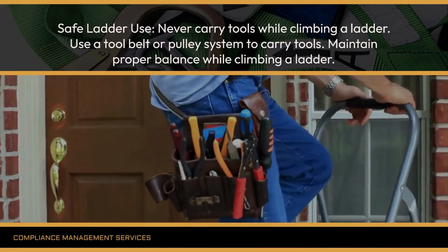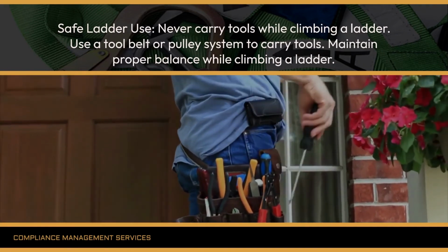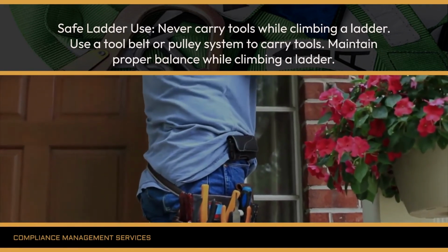Safe ladder use. Never carry tools while climbing a ladder. Use a tool belt or pulley system to carry tools. Maintain proper balance while climbing a ladder.